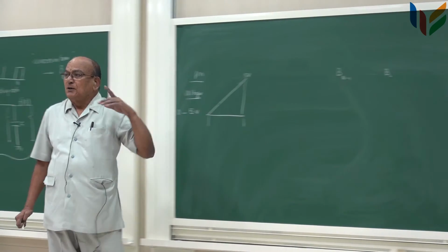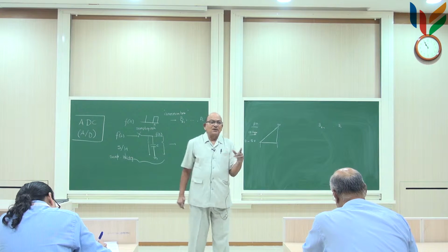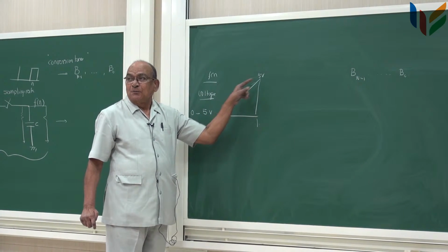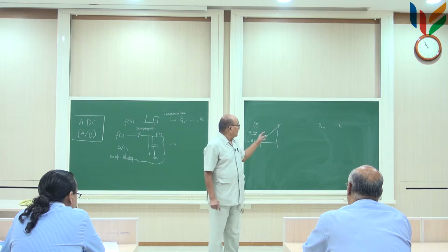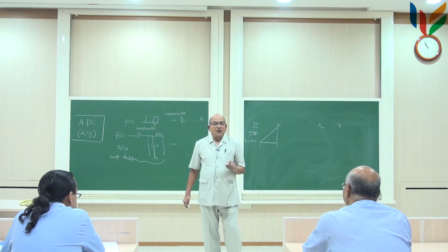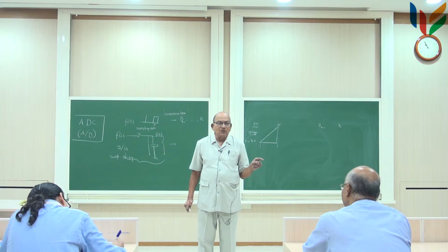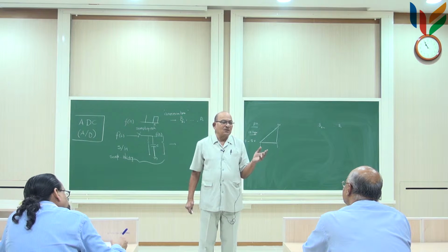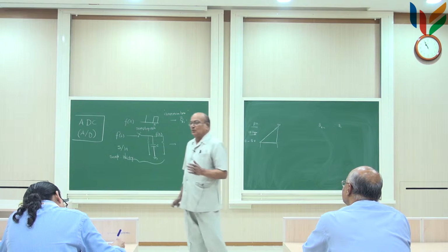Okay. So, now I have converted the voltage linearly into this. When I use the word linear, I mean that I do not allow any variations from the linearity. It should be exactly a linear curve. So, your sawtooth waveform must be as close to linear as possible. An exponential charging capacitor, even if the time constant is very large, is not a good enough sawtooth waveform. So, how to generate this sawtooth waveform?